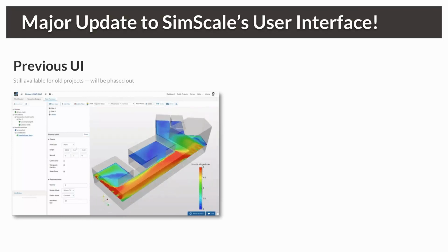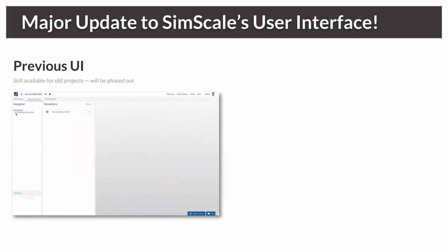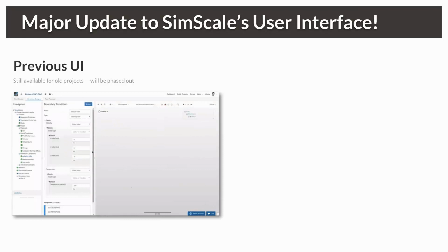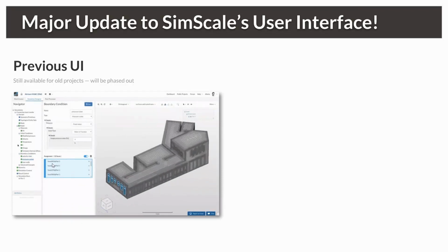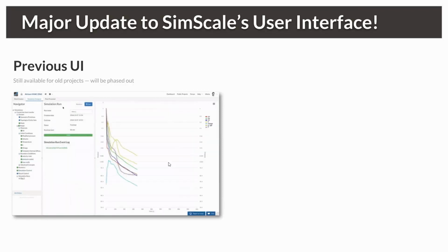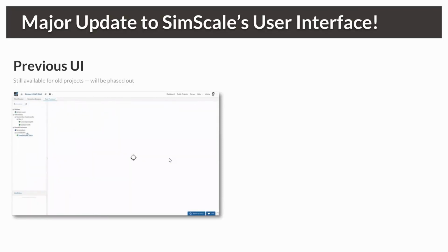And this is a thermal comfort analysis of an atrium, I think it's a commercial space, and a passive ventilation scenario is being analyzed here. So a very typical simulation project our customers would run. As you can see, now we can see the CAD model, and now the simulation setup is being shown. We can see here on the left that all the physics, all the simulation settings are being set up in this large settings panel, and I need to assign boundary conditions based on the mesh, so I can see that all boundary conditions are being defined here.